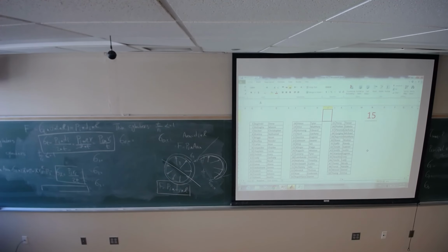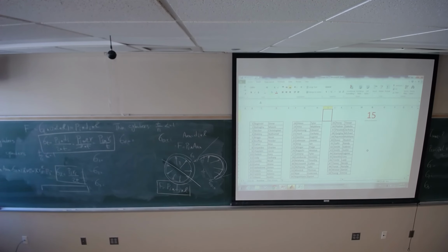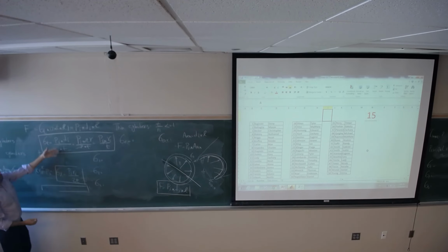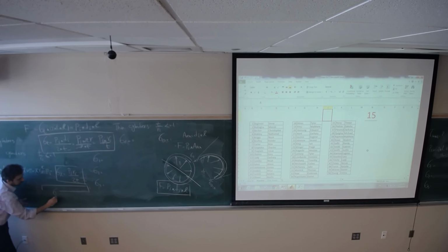Number 15. What should be the principal normal stresses? What do you think? What should be sigma 1, sigma 2, and sigma 3? Just look at this. We don't see any shear stress, which means these are the principal normal stresses. We just need to order them. So sigma R is 0, and no shear stress is showing up.